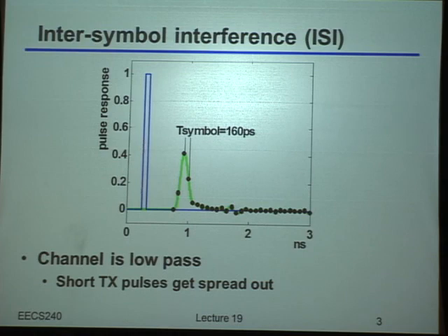So blue is what I've transmitted, green is what shows up on the receiver, and these black dots are the analog values I would get if I sampled the received signal exactly at, let's say, the quote-unquote optimum time and spaced by one T-symbol from each other. Remember, the comparator is clocked. It only looks at those particular time instances. So these black dots are the analog values you'd get at the input of the comparator if you sampled it at exactly these bit-spaced times apart from each other.